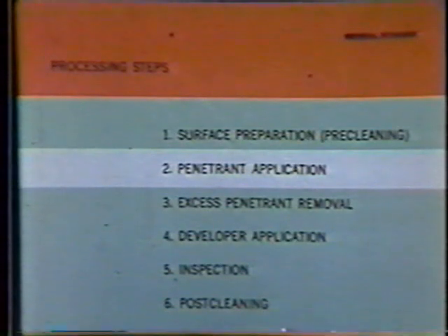Methods of penetrant application include flushing, spraying, brushing, and dipping. A uniform film of penetrant is applied and allowed to seek out and enter discontinuities. When tanks are used, the specimen is immersed in penetrant, raised, and allowed to drain. The duration, dwell time, wet penetrant must remain on test surfaces, depends on the discontinuities sought and temperature. Tight cracks require a longer dwell than open cracks. Low temperatures increase the dwell required.